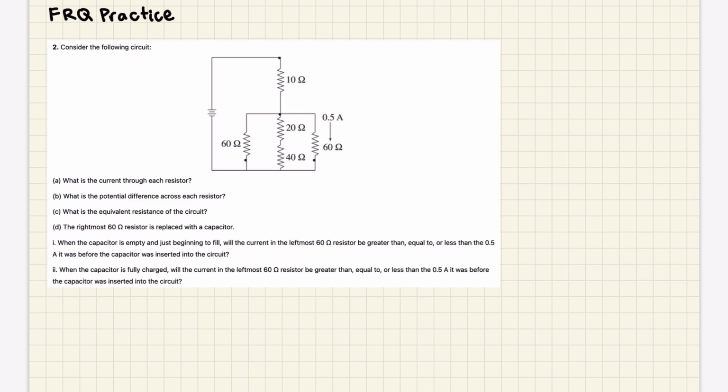And so let's see what the total resistance in each branch of this is. 60 ohms, this is 20 and 40, and in series, resistors add up to make 60 ohms. And this is also 60 ohms, meaning it's really nice. All three of them have the same resistance. And there's basically kind of a rule that current flows through the path of least resistance. That doesn't mean that all the current flows through that path. It just means that more current flows through that path.